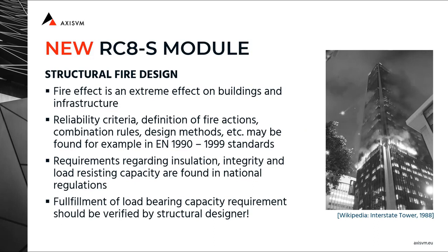Fire effect is a relatively rare extreme effect. Its extreme nature is reflected in its often extremely severe consequences and its highly nonlinear nature and structural response. The key to ensure the proper level of reliability against fire is the structural fire design. Reliability criteria, definition of fire actions, combination rules can be found in the corresponding Eurocode standards. Requirements related to different kinds of elements may be found in national regulations, such as insulation, integrity, and load-bearing capacity.